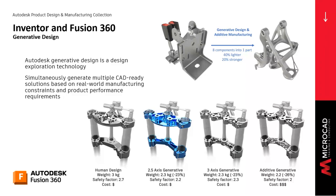Once the engineer selects what fits their needs best, the finished model can be further edited to accommodate changes as necessary. In this example, in the slide at the top, you can see that General Motors, actually, this is a seatbelt bracket, and by doing generative design, they made it 40% lighter and 20% stronger. Also, in addition to that, they made it actually easier. So instead of being 8 parts, it's now 1. So it's no longer an assembly.